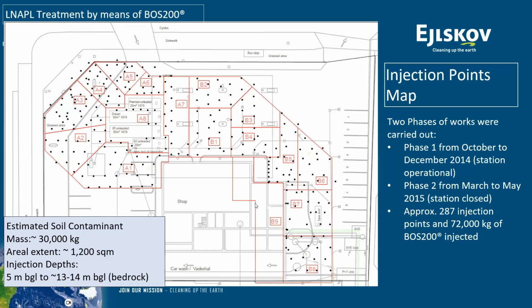Here we had a gas station where we did a large remedial design, followed by a surgical injection plan, which was divided into a total of 17 sub-areas, each sub-area with a different dosing profile and layout, in terms of criteria that were to be achieved, because it was a performance-based contract. But most importantly, we had to keep the station alive. The client didn't want to cease sales activity.